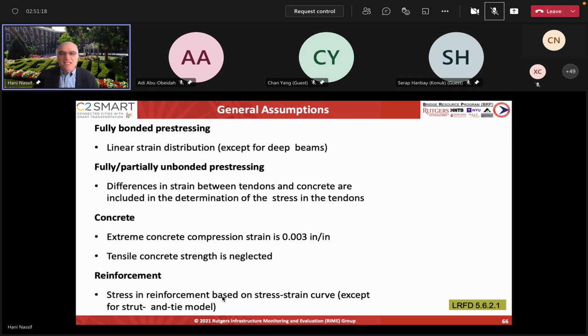Only on very long spans, longer than 140 feet, you probably get those, the 9 foot, 10 foot deep type of girder. And those usually have problems with the shear because the web has to be very thick. If you use a small web, you end up having some problems with the shear crack, I believe, especially at the end. But if you make the web thicker, then it's not possible to go that longer span. You'd have to either splice the girder or shore them or do something else.